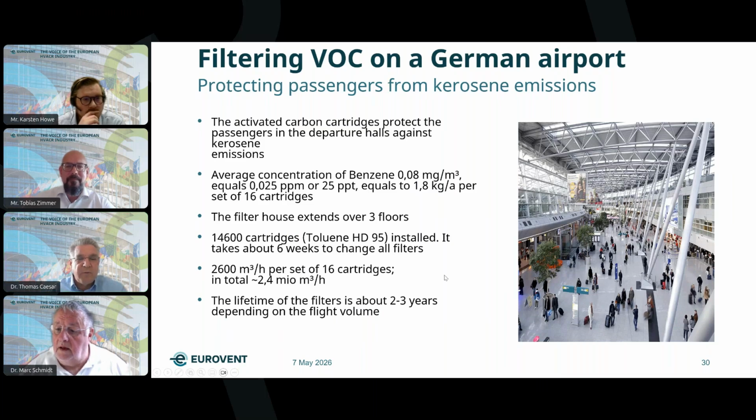Volume flow is 2,600 cubic meters per set of these 60 cartridges. So the total flow, when you look at the whole filter system, is 2.4 million cubic meters per year. And the lifetime of the filters in this example is 2 to 3 years. Next slide, please.